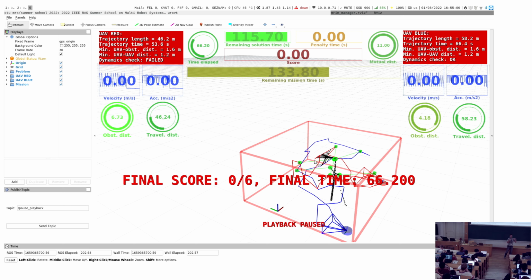So if we have a GPS receiver connected externally to the NUC computer, we can use it as well. If we have an IMU connected to the computer through USB, we can use it as well. So if you would make PIXHawk disappear, we would quite easily change from PIXHawk to another platform. We would just need to supply the attitude rate and thrust to some other platform, either using MAVROS or some other protocol. And again, getting data from PIXHawk to us, we are not strictly limited to using PIXHawk. Right now, it's the best platform for the job, but we are not tied to it.